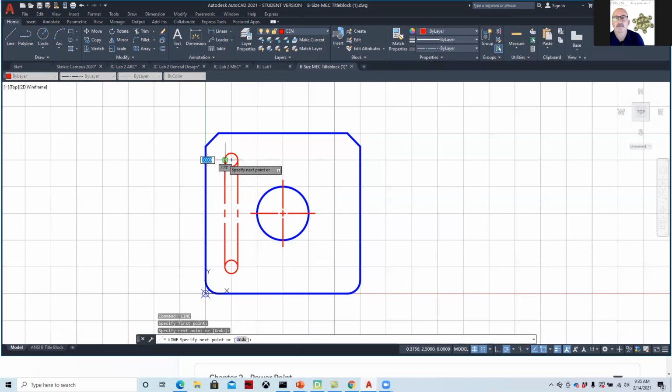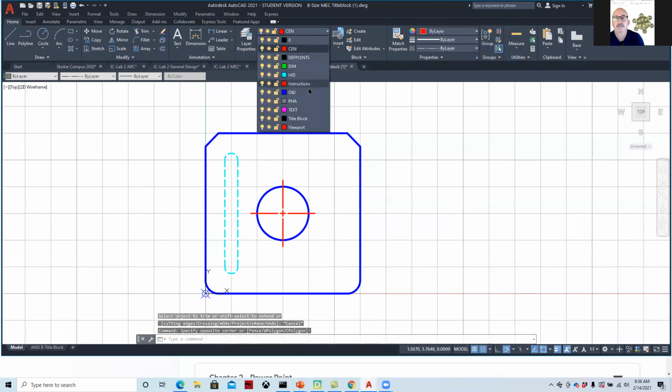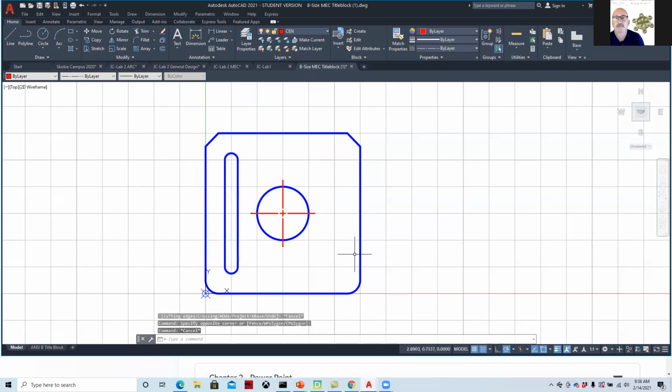so that you can own. And then we'll go in here and trim this. Trim is kind of nice. Whoops, wrong one. Undo, trim. They kind of took the way this works from SolidWorks. It's on the wrong layer. And so again, you can select things and then you can change the layers. There we go. And then if I really want to just kind of crank this out, I'll mirror it. And so we don't show you how to do all the fast ways to do it. We show you how to just make it work.